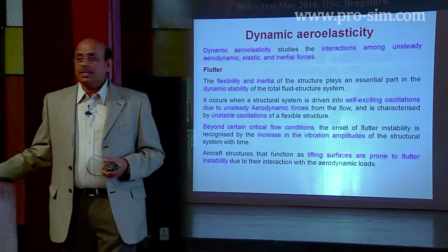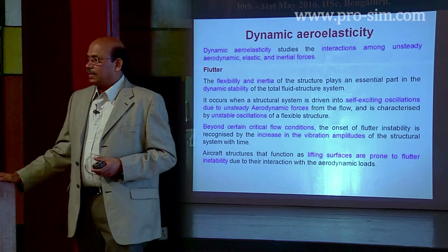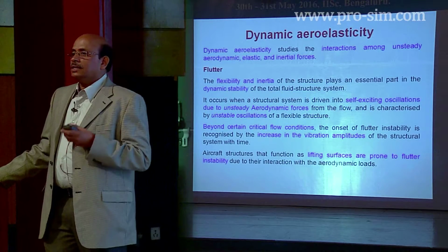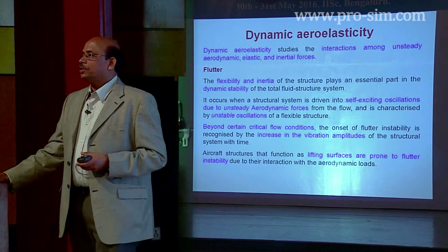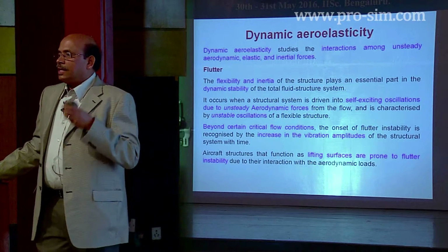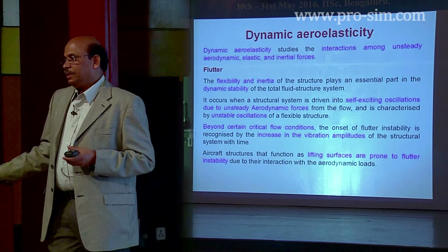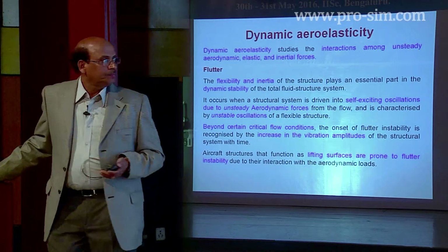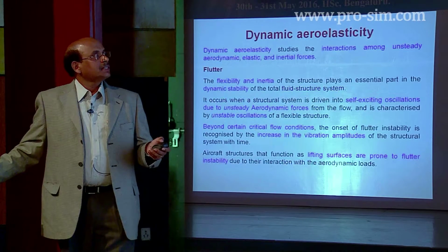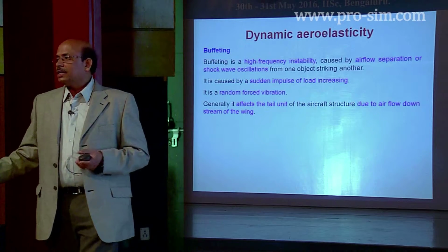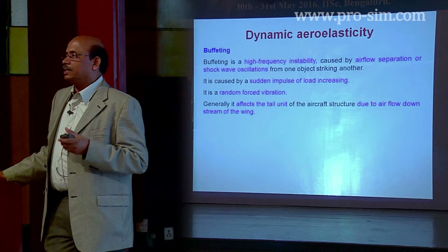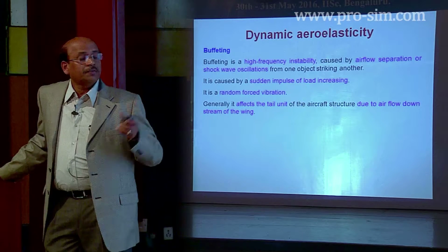Now, coming to the dynamic aeroelastic problems, there are issues known as flutter. Flutter is again a dynamic instability problem. Here, with increased aircraft speeds, there is going to be a dynamic instability issue coming into the picture, wherein there is going to be increased amplitude of vibrations of the aircraft. That leads to the phenomenon of flutter. There are other issues such as buffeting and aeroelastic gust, and several other related dynamic aeroelastic problems are also encountered in the field of aeroelasticity.